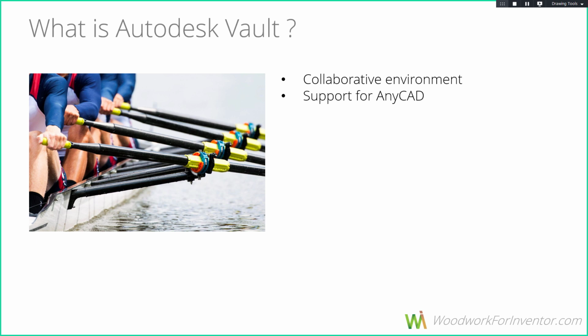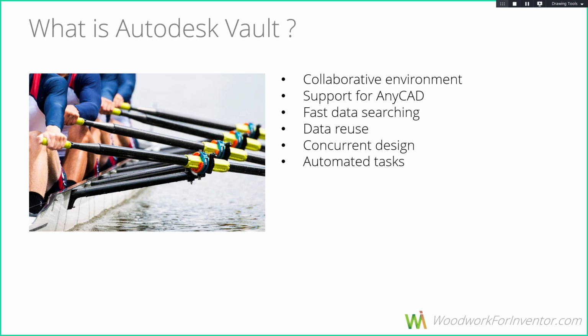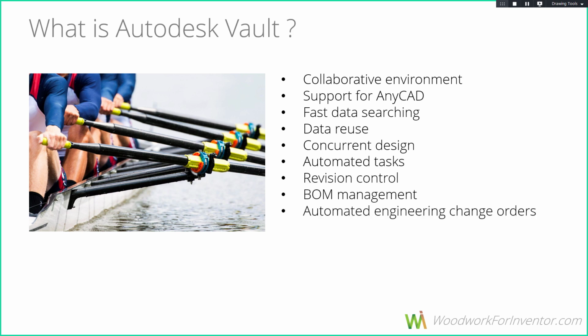We have support of AnyCAD, which allows you to import and export geometry in different file formats. You can quickly look for the data, reuse the data you found. We can have collaboration teams which work on the same design at the same time. Some of the tasks may be automated. You can have a revision, you can manage the BOM, you can automate ECO, and in some cases, Vault can simplify your ERP integration.